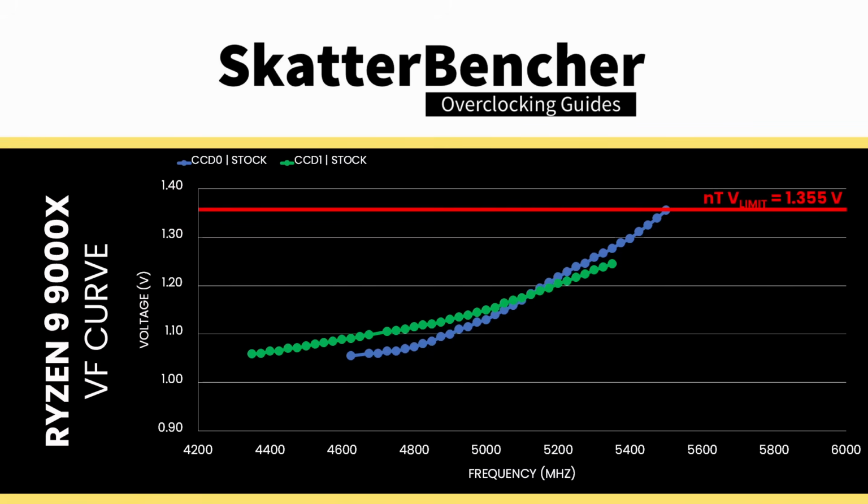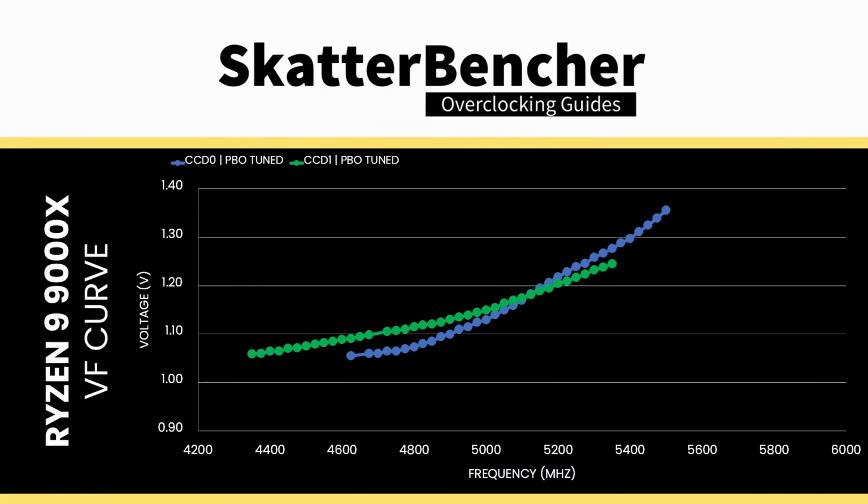The Precision Boost 2 algorithm utilizes the VF curve to find what's the maximum possible frequency at 1.355 volt. As I showed just a minute ago, we can use the Fmax Boost Override tool to increase the Fmax by another 200 MHz and extend the maximum allowed voltage using scalar.